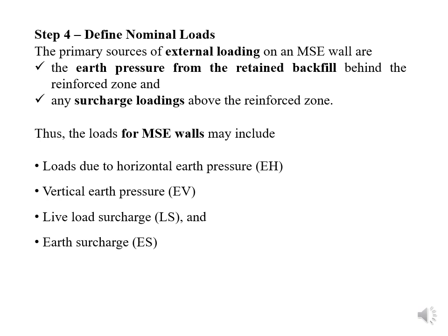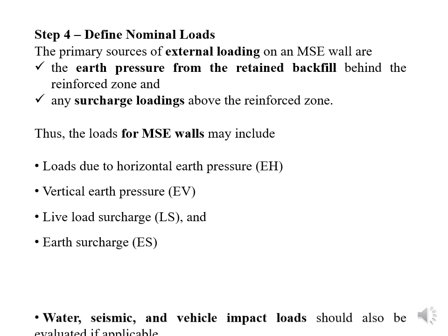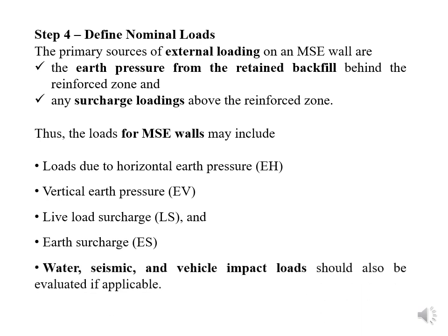Earth surcharge, if you put some earth on top of the retaining wall, you also have to consider. In addition, water, seismic and vehicle impact loads should also be evaluated if applicable for your mechanically stabilized earth wall, which is also called a soil reinforced wall, right?